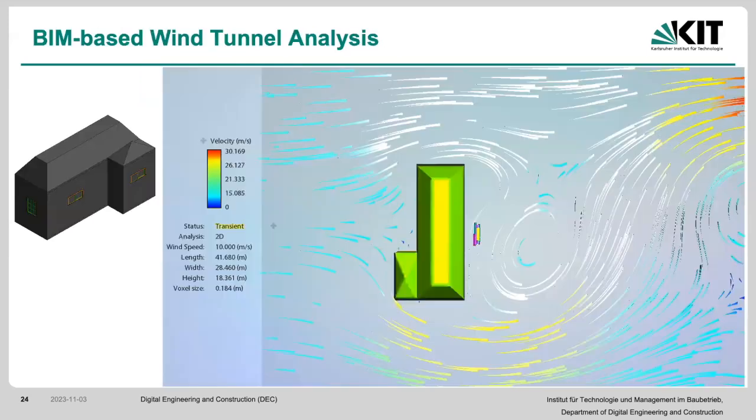Okay. So, wind simulation. For instance, I've done this simulation using Flow Design. Where is this going to be useful? Obviously, in areas where wind is going to be of essence. Mostly, wind is going to be of essence if you have a taller building. Let's say the fundamental frequency becomes important because it's a dynamic type of loading. And taller buildings normally have lower fundamental frequencies. So we want to make sure that whatever we're designing is going to satisfy what we have at the end.